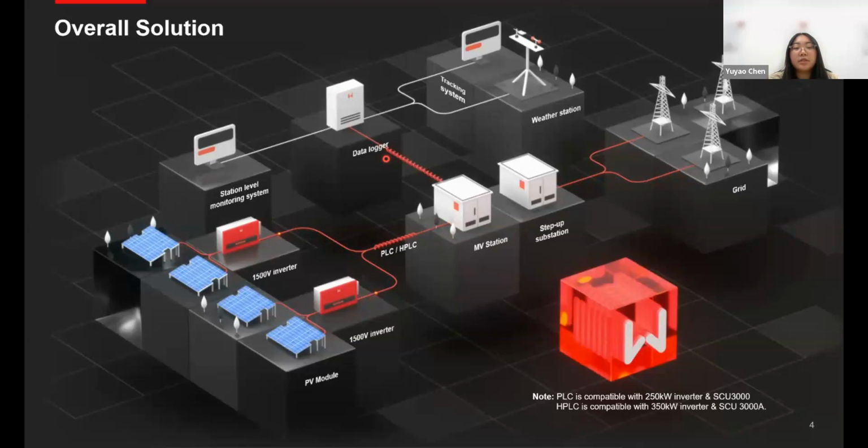The inverter converts the energy to AC power, and then we combine all the inverters, and the output goes to the transformer. So this is the transformer station. It collects several string inverters from their AC output, and then does the voltage step up.